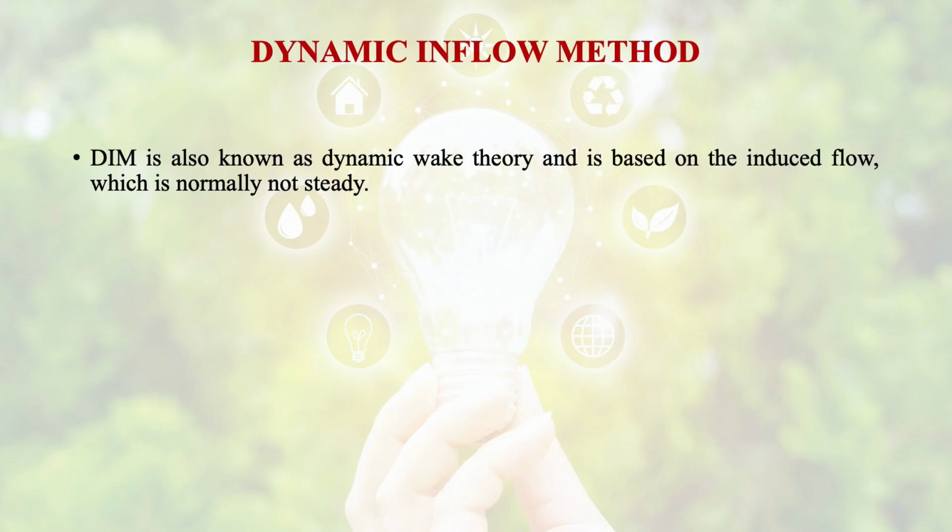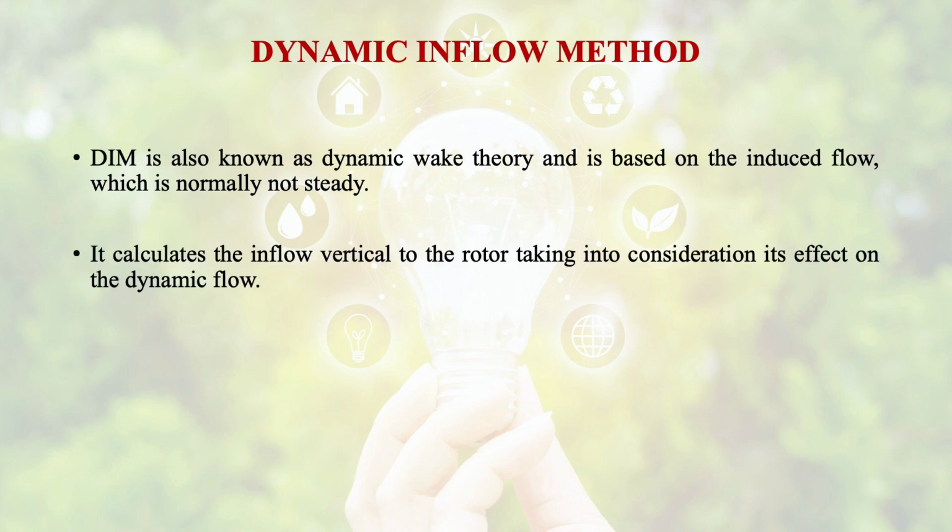This theory is also known as the dynamic wake theory and is based on the induced flow, which is normally not steady. It calculates the inflow vertical to the rotor, taking into consideration its effect on the dynamic flow.